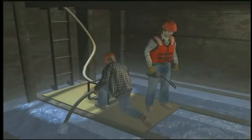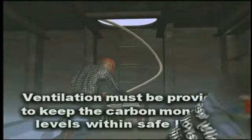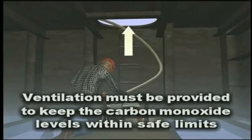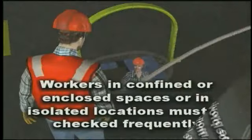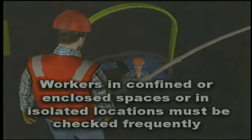When using internal combustion engines exhausted below decks, the space must be periodically tested by a shipyard competent person to ensure that dangerous levels of carbon monoxide do not develop. Ventilation must be provided to maintain the oxygen level and keep carbon monoxide below hazardous levels in spaces where internal combustion engines are used. Workers in confined or enclosed spaces or in isolated locations must be checked frequently.